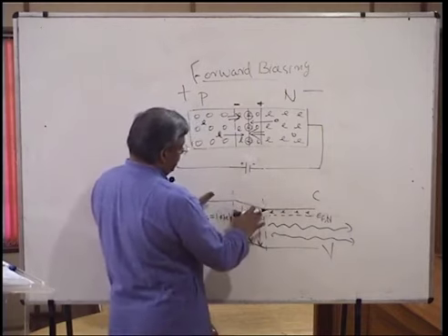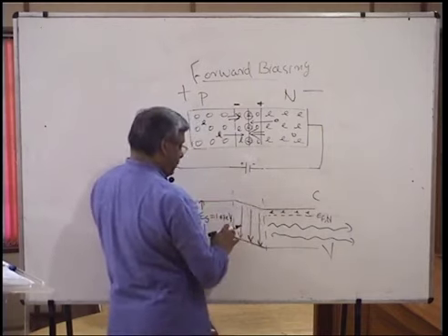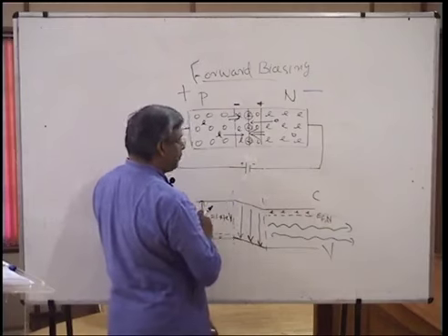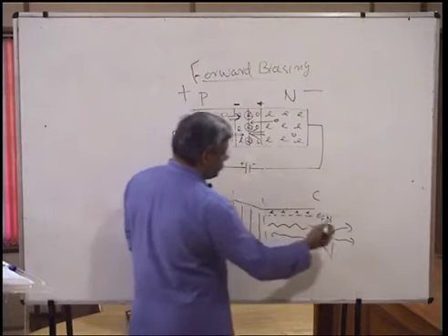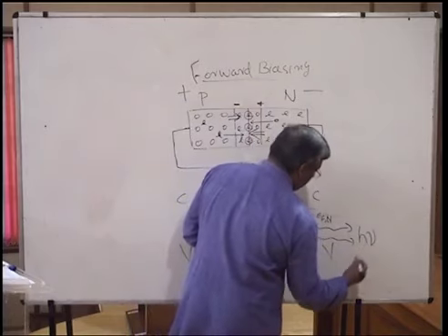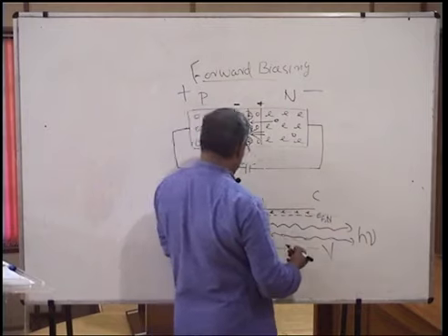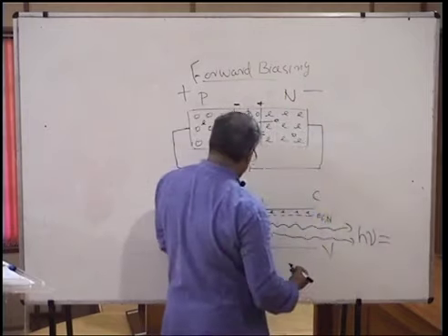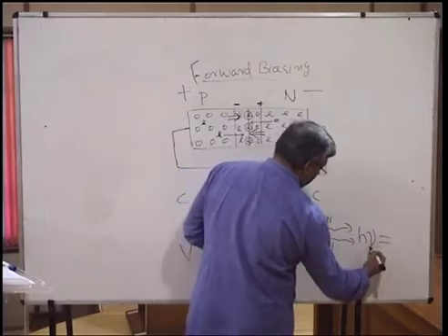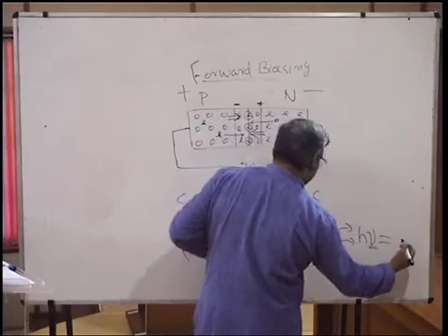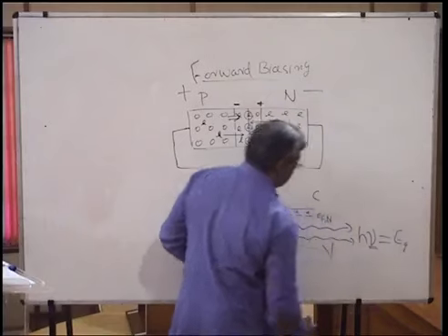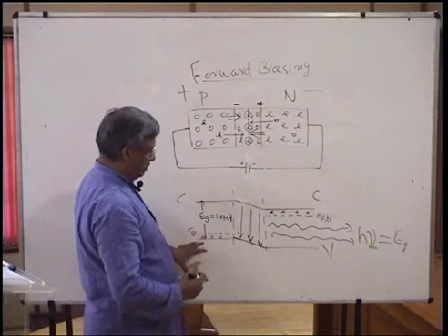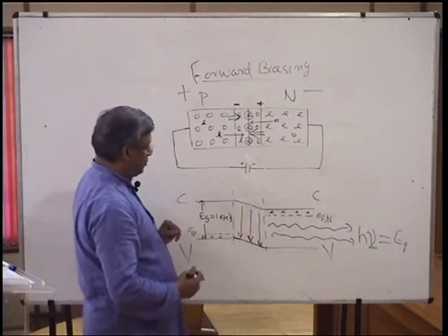electrons in the depletion layer with the holes in the valence band of the depletion layer, leading to the production or emission of radiation, which has a frequency corresponding to the energy gap of this particular PN junction material. So, depending on this material, you will have the light. So, that's the important thing.